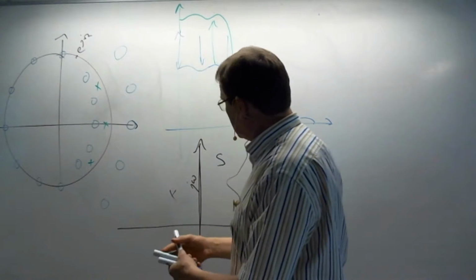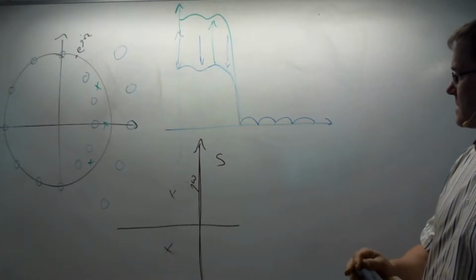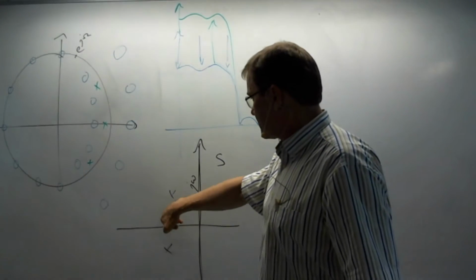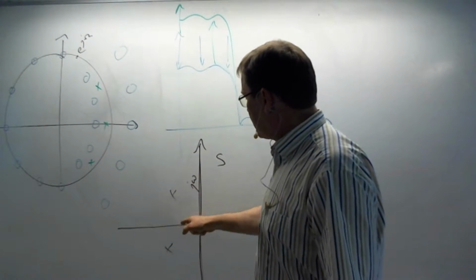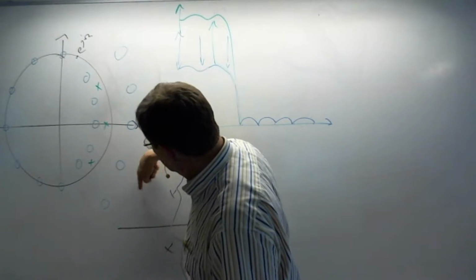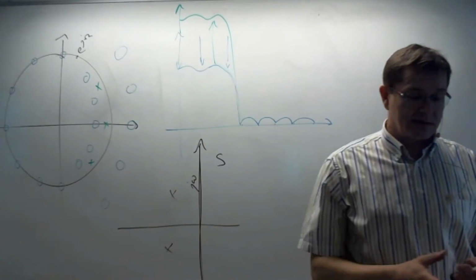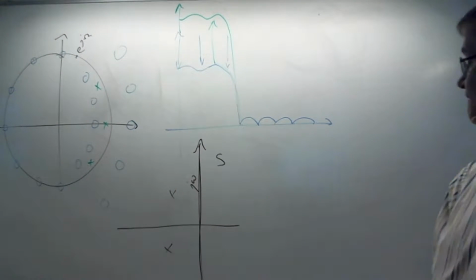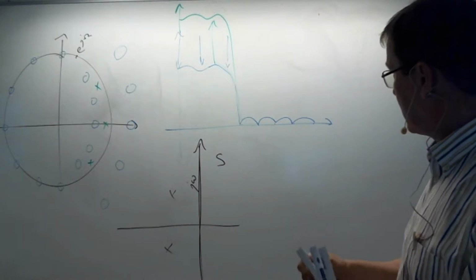Basically, this bilinear transformation is the way to transform these pole locations, which are in the analog domain, in a certain way so that they fit into the Z plane, and there's only a simple trick.